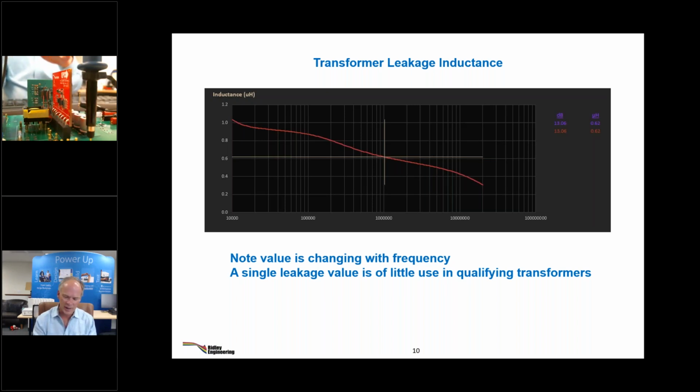You can try doing, okay, this was continuous mode. What if I wound one for discontinuous mode? What's the efficiency going to be if I go into discontinuous mode and I manage to get valley switching in there? With the design tools here, instead of agonizing over the design, which is really quite easy, and everybody in magnetics knows that these flyback transformers are really easy to put together, now you can just open up your Horizon and say, okay, how can I creatively rewind that flyback?